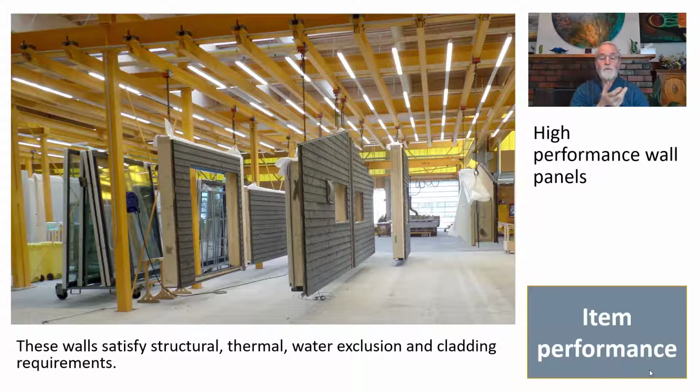It includes windows and doors. It includes all your cladding. It includes the basic servicing, electrics, etc. And then it's brought to site. And these things then assemble in a precise manner to give you an enclosed building very quickly. So this is obviously a relatively high performance panel, even though the shape of the panel and its form is relatively simple. They're a flat object.